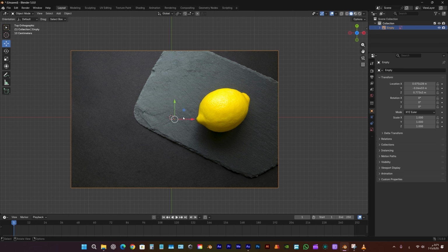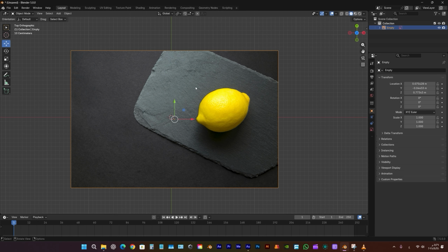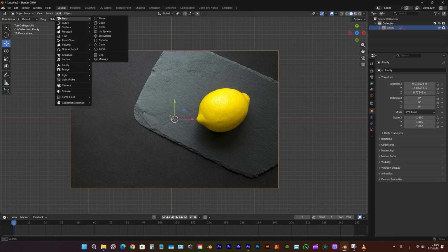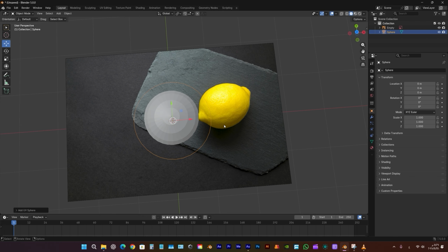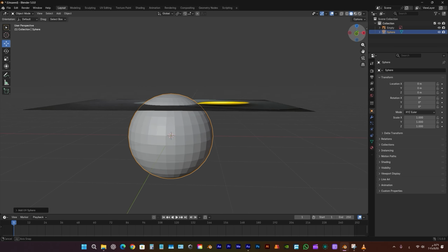I'll press Z to switch views. I'm just moving around the software here, pressing Z like this. Right now, we are in the top view, looking at the object from a top-down perspective. Go to the menu, click Add, go down to Mesh, and then what do we choose? We'll choose a UV sphere. Of course, when you press and hold the middle mouse button, the scroll wheel, and move it, the view rotates like this. You can also rotate from here, no problem.